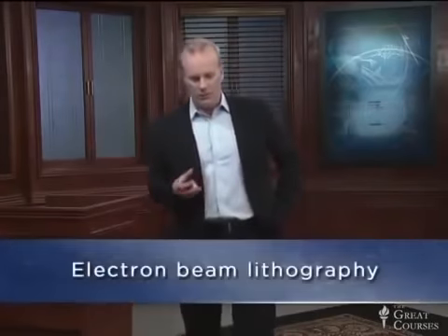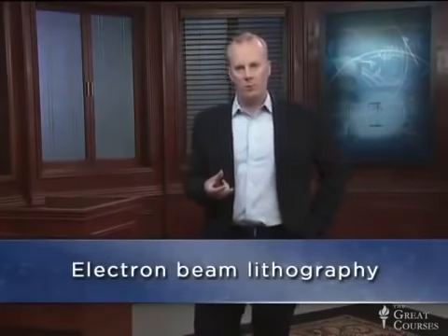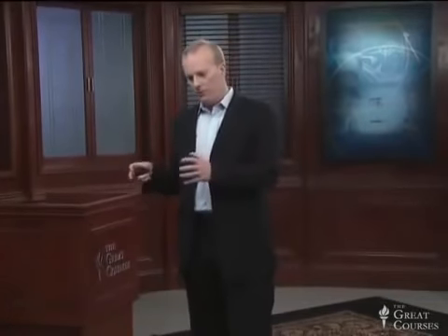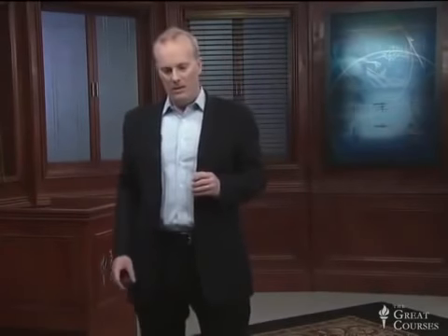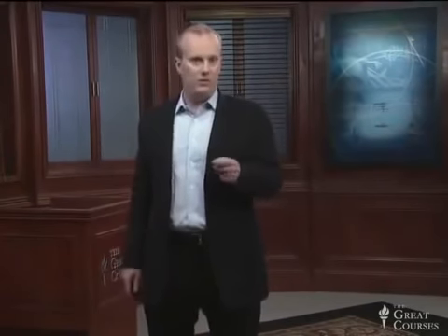Well, what's interesting about that remark is that that's precisely how one of the major forms of crafting matter at the nanoscale did emerge. Electron beam lithography, which is one of the ways in which we get beyond the limits of photolithography, the resolution that's available there, the optical resolution, and into the electron resolution scale. That is achieved essentially by reversing the operation of an electron microscope into write mode instead of read mode.